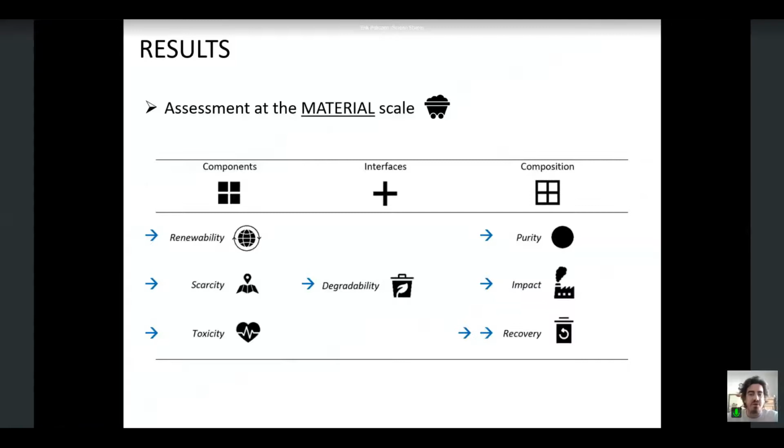And third, a great opportunity is the recovery of excavation soil from building sites to manufacture earthen building materials. However, it is very important that no stabilizers such as cement are used, because stabilizers are often added to improve durability or strength, but this comes at the cost of all these circular qualities at once.